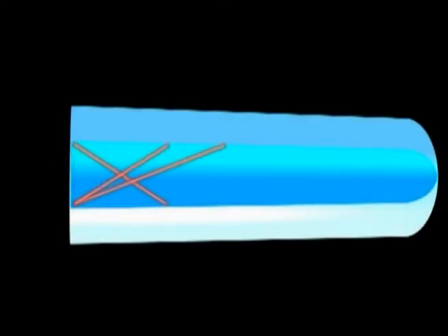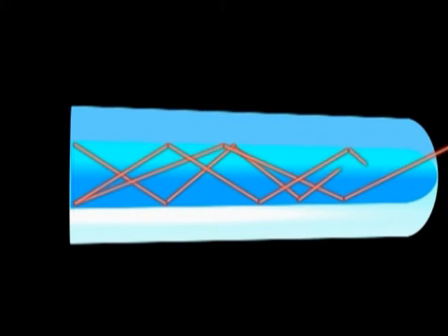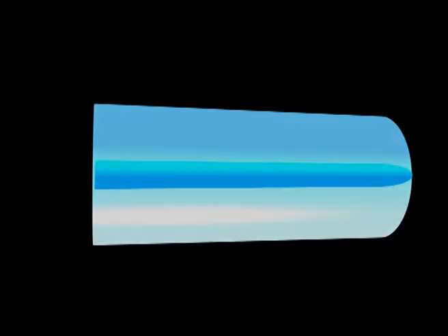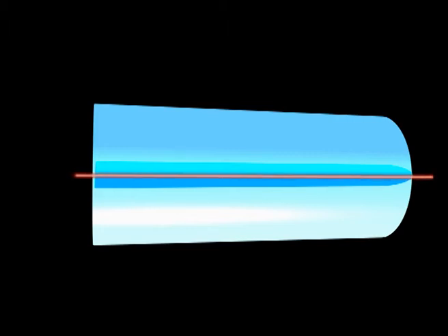There are two types of fibers, multimode and single-mode fibers. Multimode fiber allows the reflection of the light beam by many possible paths, that is to say, by many light modes. However, it supports less distance. Single-mode fiber allows a single mode or path for light, which can travel greater distances.